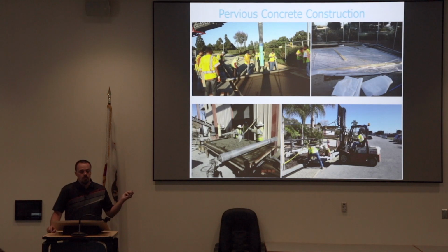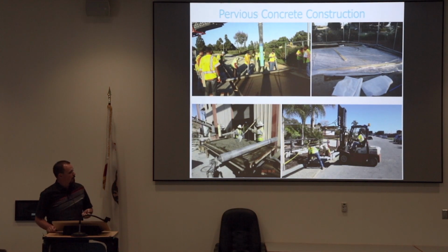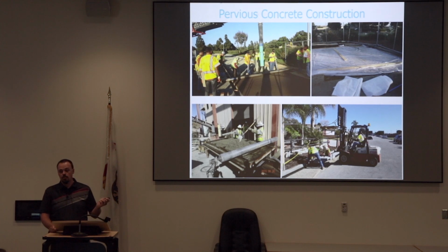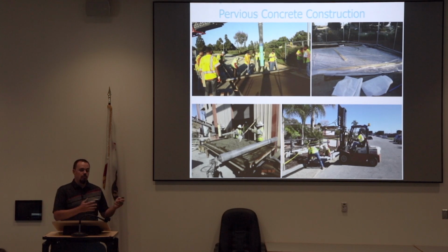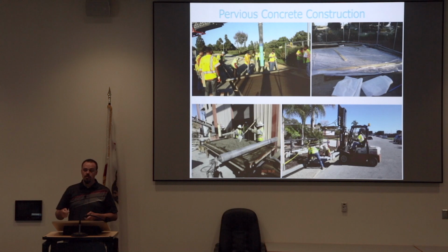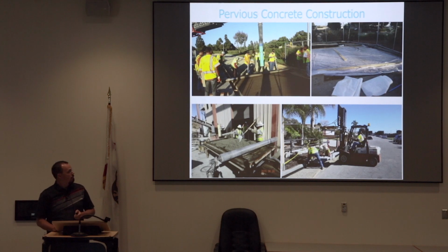At the time, these weren't really available, but for a grant project out in El Rio, the community of El Rio, we brought a company called Stormwater out. They do this stuff in Maine, and they set up with Precon in Simi Valley to start creating modular panels. So now you have them set in a controlled environment. If anyone's ever worked with pervious concrete, it's extremely difficult and delicate. Too much working in the field closes the voids and it won't infiltrate. So it just makes sense to make a modular system like this that you can utilize.